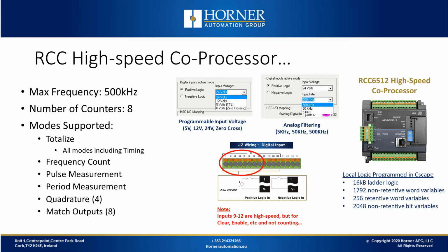From a logic standpoint, this unit is programmable in ladder logic, but is slightly more limited than most of our products in terms of the amount of logic and variables that it supports. It supports up to 16K of ladder with a limited number of variables, about 1800 that are non-retentive and 256 that are retentive. We've got 2K non-retentive bit types available as well.